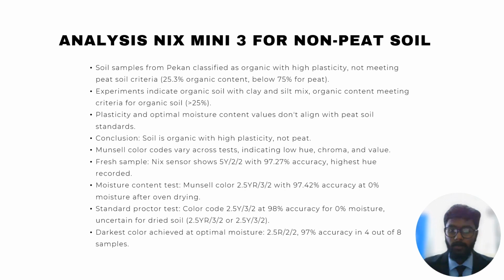So the final analysis for the Nix color sensor color code classification is that the peat soil sample is classified as organic with high plasticity, not meeting the peat soil criteria. The experiment indicates organic soil with a clay and silt mix, where organic content meeting the criteria for organic soil should be more than 25%. Plasticity and the optimal moisture content values don't align with the peat soil standards. So the conclusion from this experiment is that the soil is organic with high plasticity and not peat.